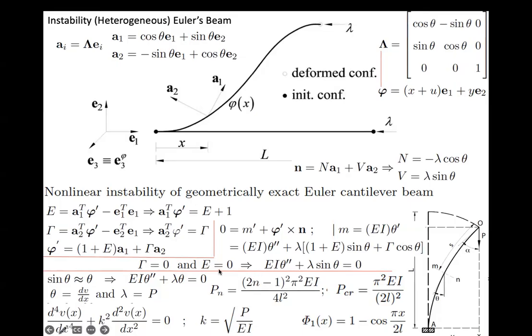First, you have something called Kirchhoff beam. When you simply kill the shear strain, you still have your axial strain. And some people were developing this recently for something like a very thin, slender structure, and you study something like a structure of the lungs or whatever. This I was recently an expert in a thesis in Dublin, in Ireland. They're also developing this for modeling this type of wires with different types of thin fibers put together. And basically this was also a Cosserat beam, but what Euler was studying was Euler elastica.